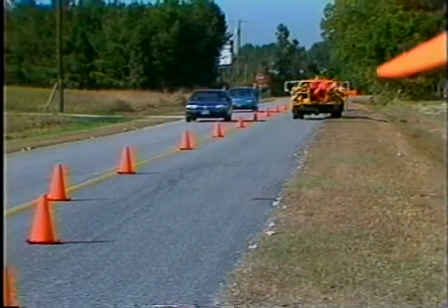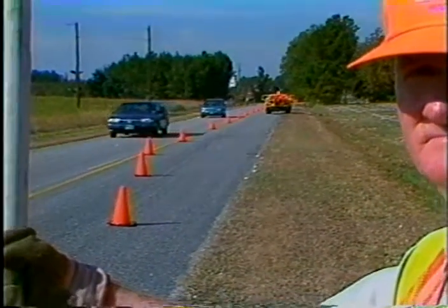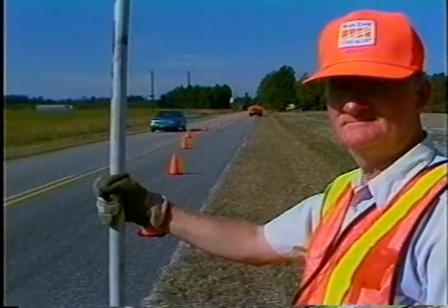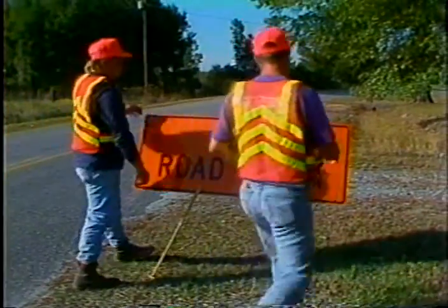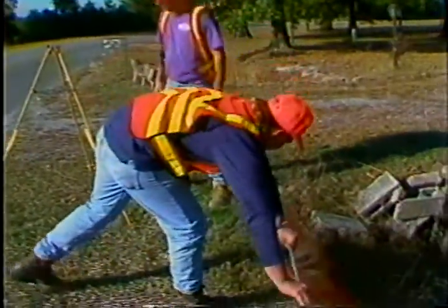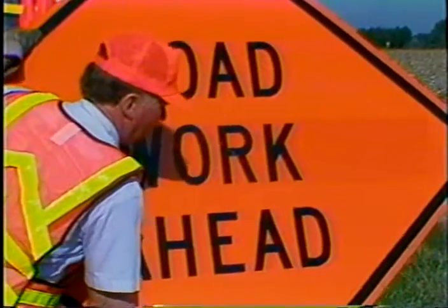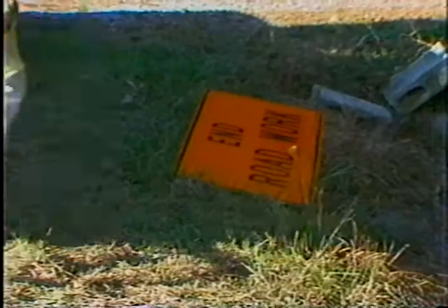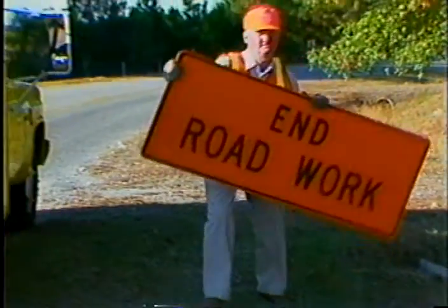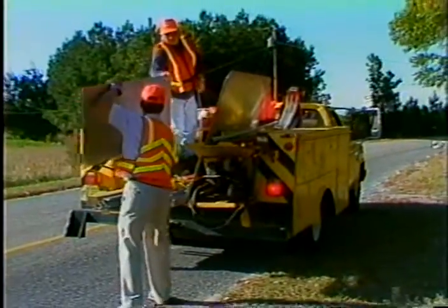If the traffic control scheme gives the driver the necessary warning and guidance, you and your co-workers will be providing the best protection for yourselves while working on or near the roadway. As soon as the work is completed, remove the traffic control devices in the reverse order of installation, starting with the termination area and proceeding back to the first device installed. A good technique for removing the control devices is to first place them on the shoulder of the roadway and then pick them up in the direction of traffic flow.